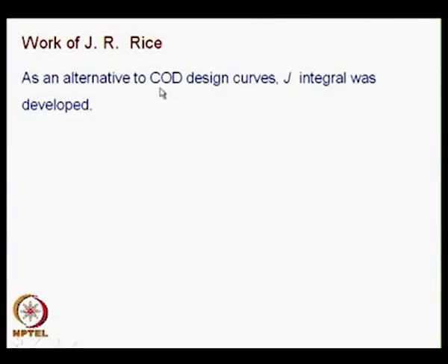And if you look at the literature, the J integral is credited to J.R. Rice. And historically, if you look at the concept of COD or CTOD has been developed earlier than J. Around 1961, Wells and Cottrell have reported how to account for problems involving larger zones of plasticity, because LEFM was confined to very small plastic zone.